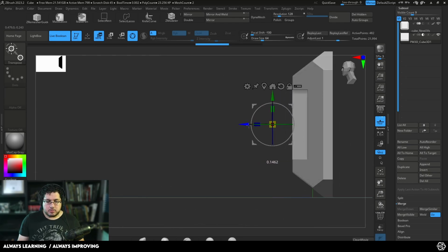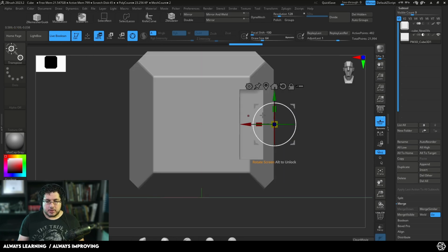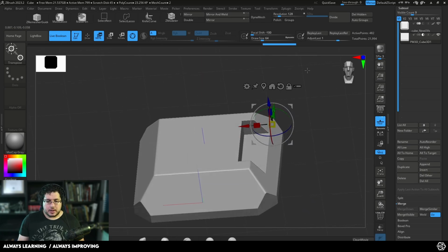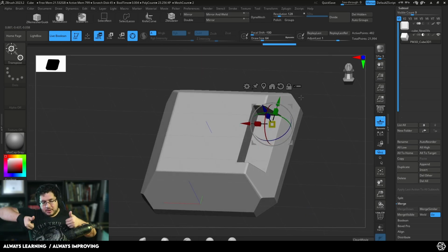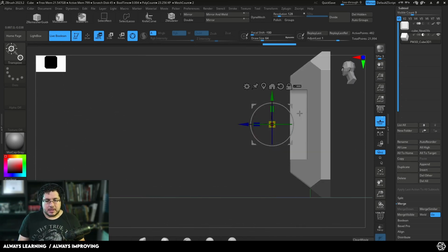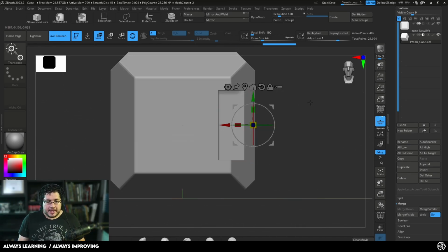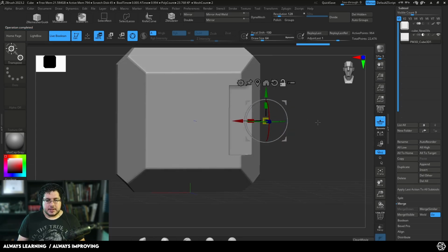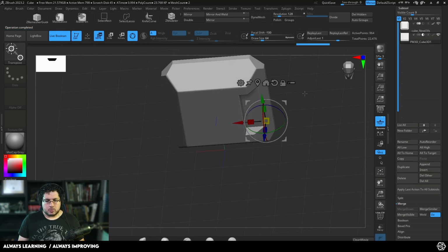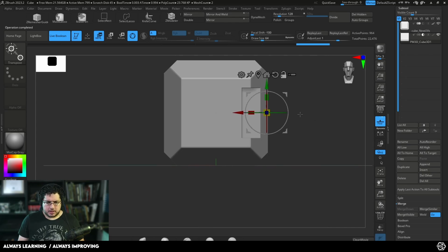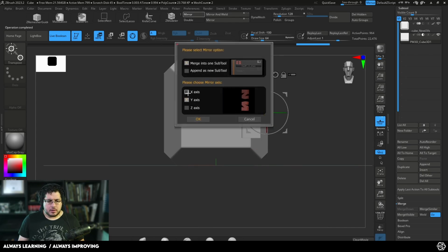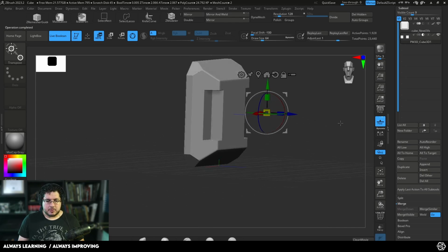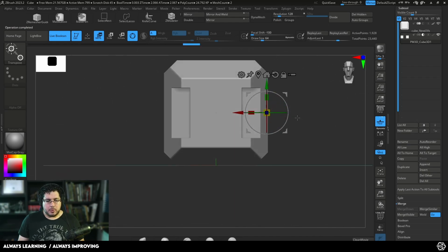So I want this one to be, again, roughly around the center line, right around there, and going probably around there, just to generate, you know, how you can sometimes press these things and they just pop open or something like that. Well, that's kind of the effect that we're going for in this particular case. And again, I'm just going to mirror this to the x-axis. Oh, did not work. It's very weird. It should have worked right there. Oh, I did the y-axis. There we go. X-axis. Perfect. And by doing that, we get both cuts on both of the elements.